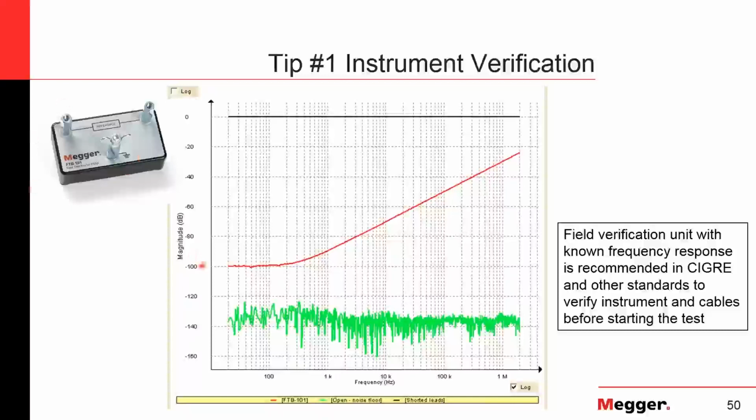If for some reason you forgot this thing, there's some other tests you can do too to check. One is shorting the leads together, and then you'll expect this typical 0 dB response. So very little change between the output and the input, especially when you look at the full scale here.